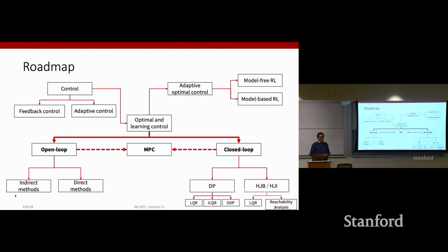But at the same time, chemical processes typically evolve on a slower time scale, multiple seconds. So even though MPC often relies on online optimization, and at the time the computers were not particularly fast, people could still solve those optimization problems at a level of a few seconds. So it was just a sweet spot. There was a need, and the problem itself was well attuned to solving optimization problems at maybe 0.5 hertz or 0.1 hertz.